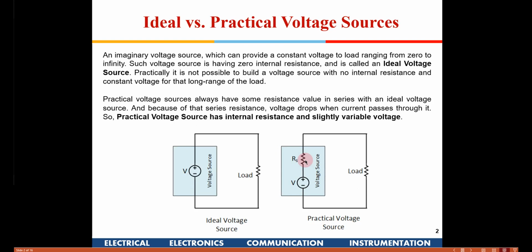Okay, so if it's a pure inductor where you have only an L value, then it is an ideal inductor. Whereas practically, whenever you have an inductor coil, you will have some resistance because of the copper winding, so a series resistance will come. So what is the limitation which happens due to this resistance Rs in series? Suppose it is a 1 ohm series resistance. If you are connecting a 1 k load resistance here, that 1 ohm is almost negligible compared to 1 kilo ohm, so it will have a very negligible effect.